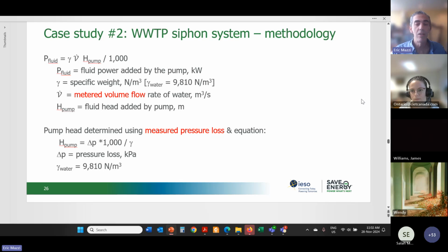But the key question, Salah, is what is the appropriate minimum duration of the reporting period? For buildings and HVAC processes, because they are almost always based on outdoor air temperature, you really need 12 months to capture all seasonal and shoulder season effects.